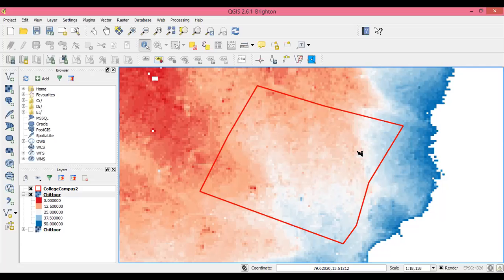That will give you a rainfall intensity, the peak rainfall intensity, right? If the 10 centimeters of rainfall happened in 1 hour, then your I, which is the I that goes into your equation, will be 10 centimeters per hour. You put that into the equation, you solve for it, you get the peak runoff rate, and that is the answer that you're looking for, right?